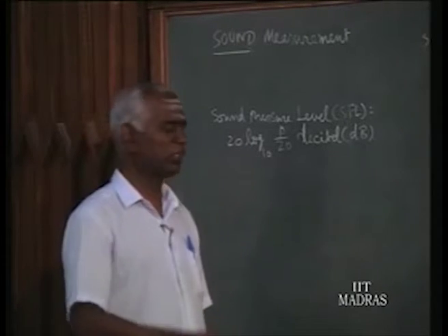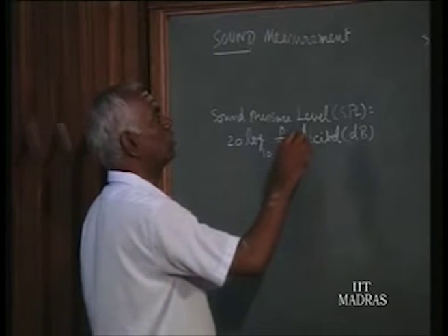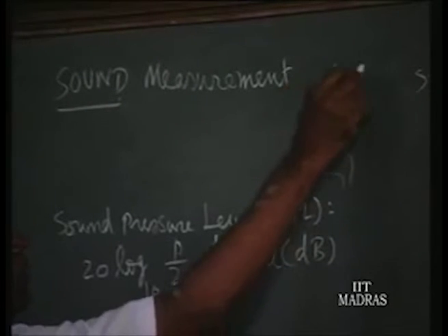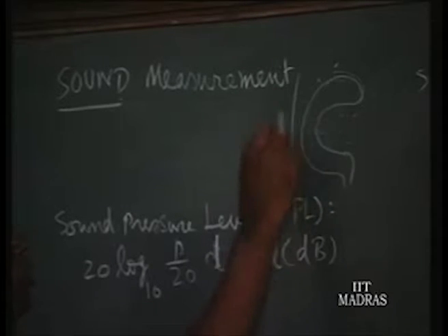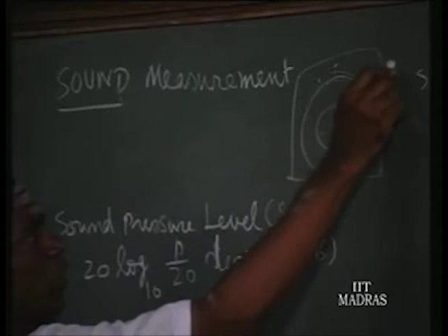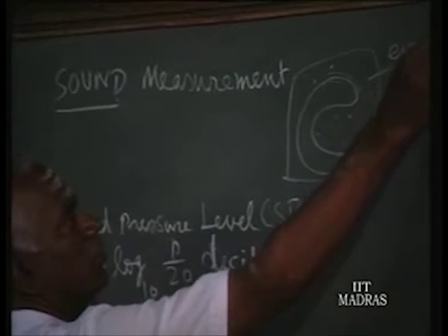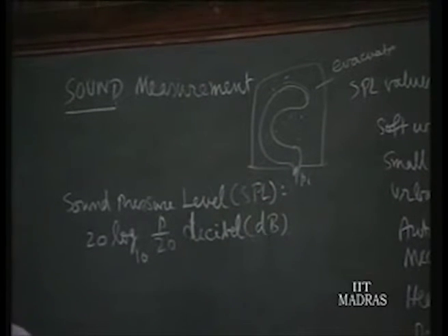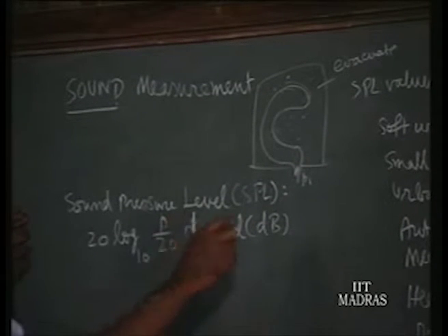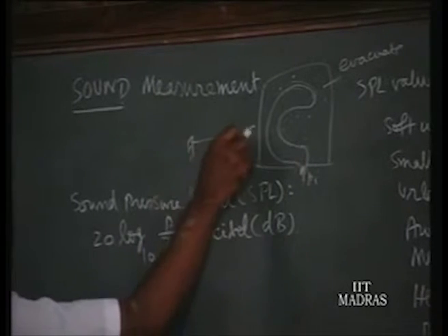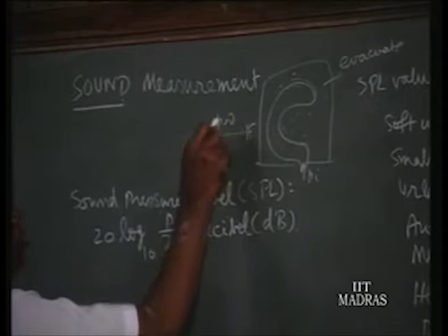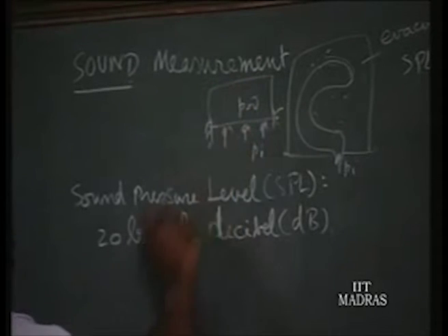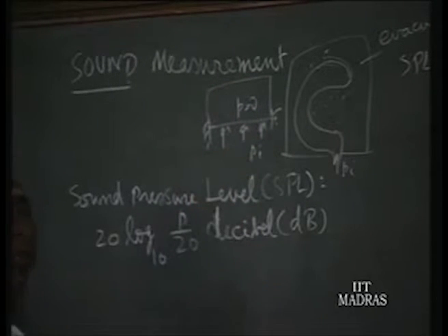If you take the Bourdon tube, this is what you have seen. If we put it in atmospheric conditions into a casing, and you evacuate the surrounding in which the Bourdon tube is put, then the Bourdon tube itself can measure the low pressure or vacuum pressure. Similarly, when we have a diaphragm, and on this side we say P is equal to 0 vacuum, and here it is some pressure Pi, then we can measure the vacuum pressure also, lower than atmospheric conditions.